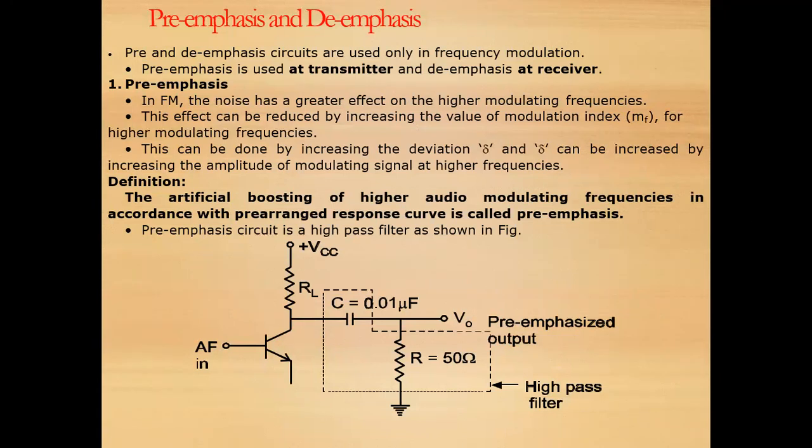Coming to the next topic, we need pre-emphasis and de-emphasis. Actually, these pre-emphasis and de-emphasis circuits are used only in frequency modulation, while transmitting and receiving our information. At the transmission side, we will be using pre-emphasis. At the receiving side, we will be using de-emphasis.